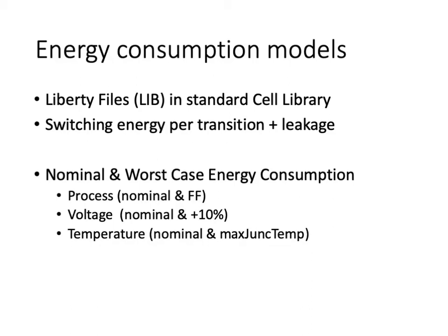In the previous lesson, we saw how to estimate toggle rates and activity factors in each of the logic gates within a Verilog or VHDL RTL design, and that would, together with the capacitance at each output, the toggle rate, and the power supply voltage, allow us to estimate the dynamic power.